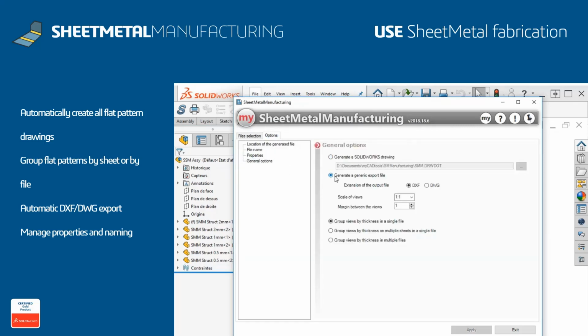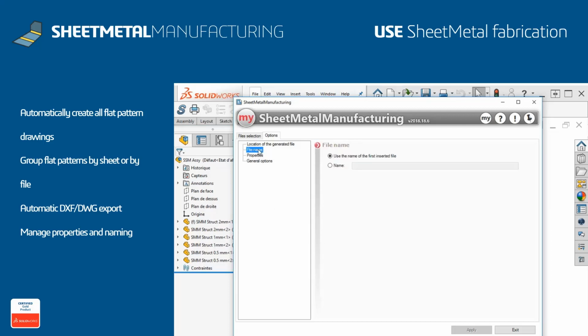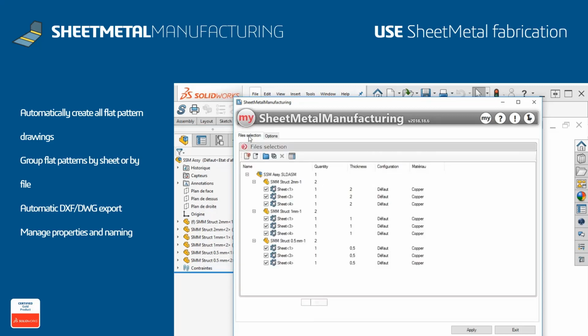In the options, the results can either be a SOLIDWORKS drawing or a DXF or DWG file. Sheet metal manufacturing groups together the panels by thickness, or in a single sheet, a single file, or different sheets or different files. It's possible to display the sheet metal properties below for each unfolded view. Finally, you can choose your file name and destination folder.